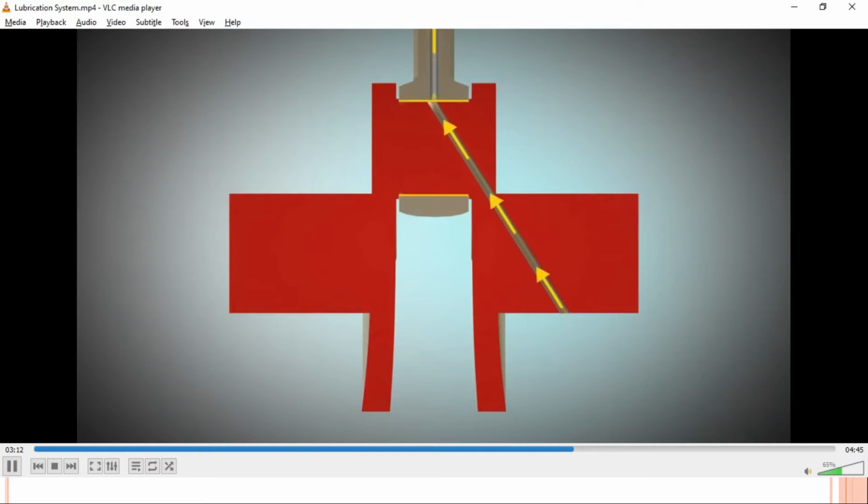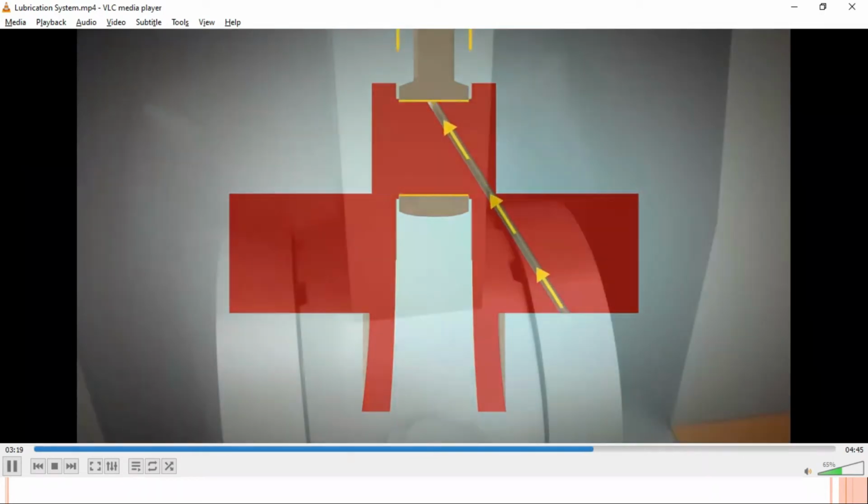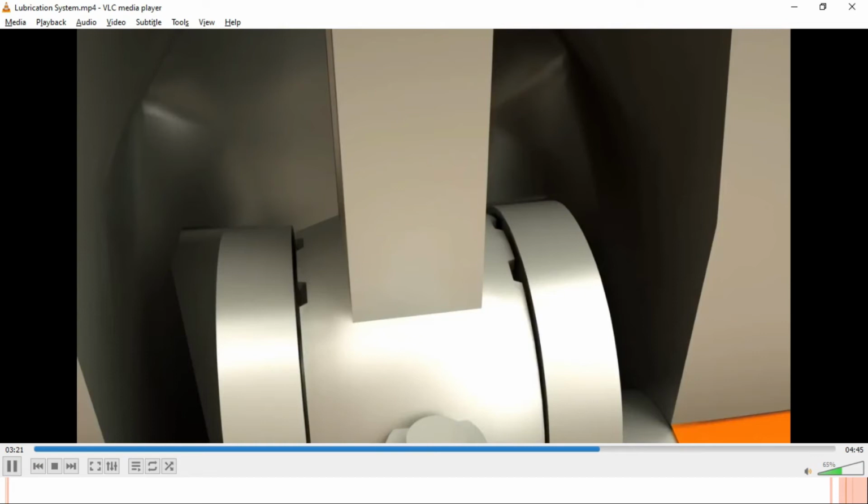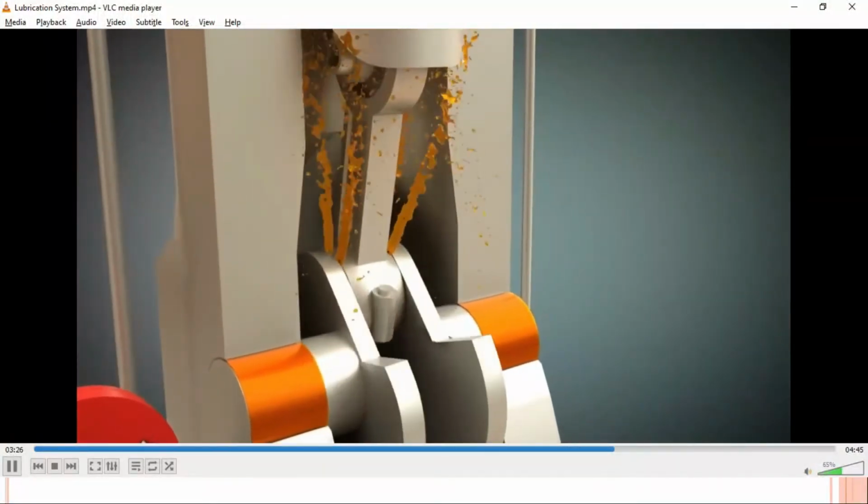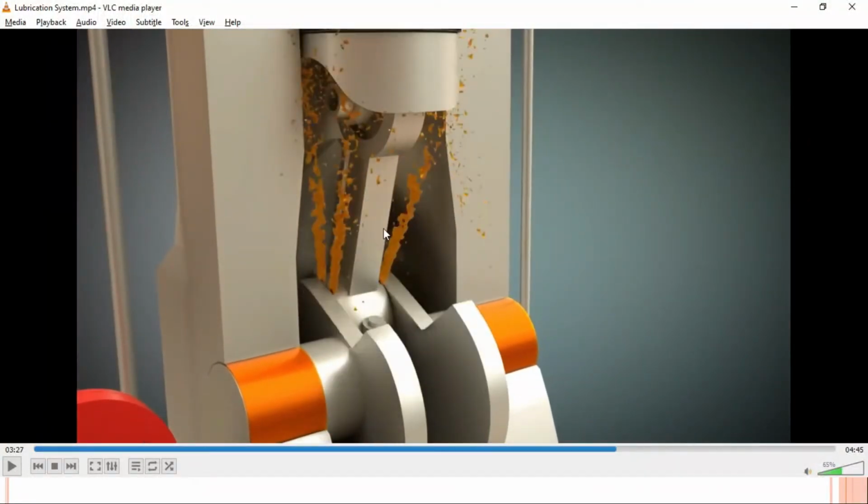For gasoline engines, on the other hand, the oil which splashes out of the sides of the bearing is used to cool and lubricate the piston, pin, and cylinder. This can also help to transport the oil to the desired parts and spots. It is very important to understand that in gasoline engines we usually do not have oil passages through the connecting rod going up to lubricate the gudgeon pin, or small end bearing.